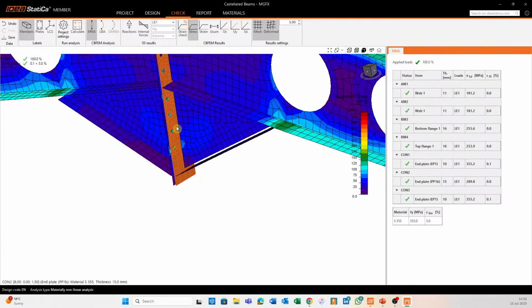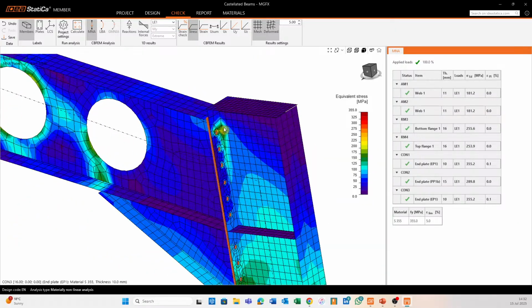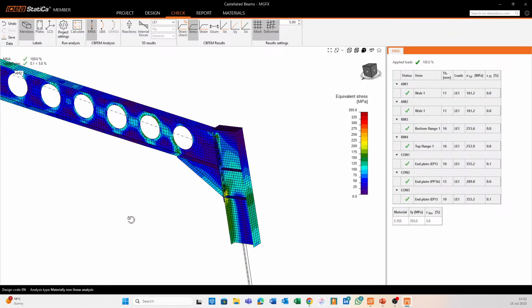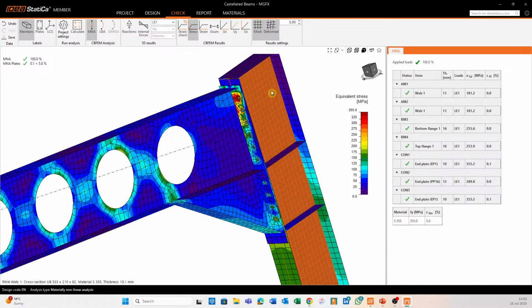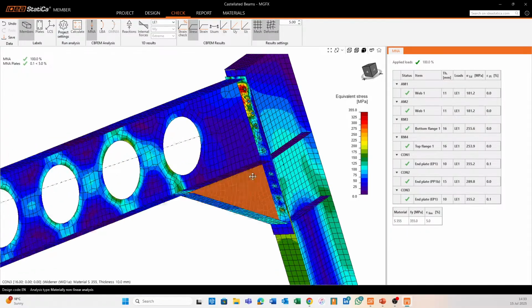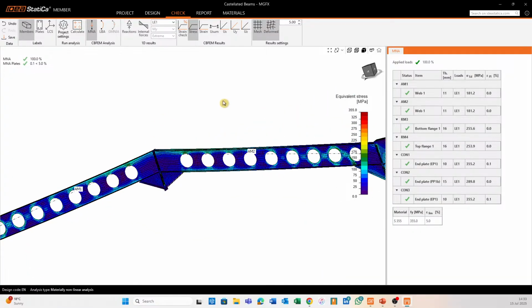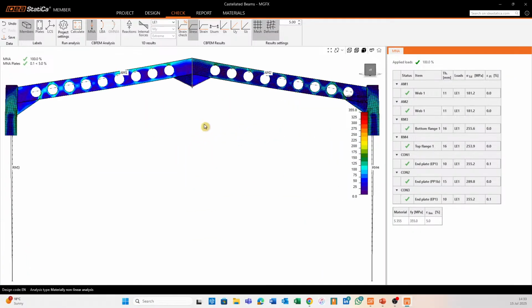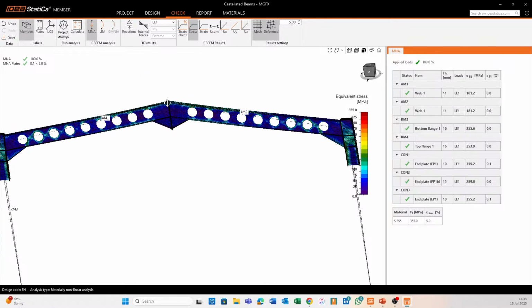It seems like it's in our apex, maybe. All right, maybe at these bolt locations, but there's nowhere where... okay, there we go. Okay, so at those end plates, that's most likely where we have exceeded that plastic strain. But we are not done. For all intents and purposes, this is just the first check.